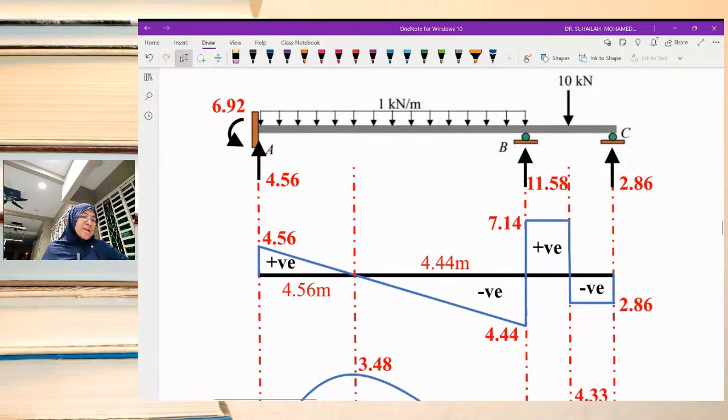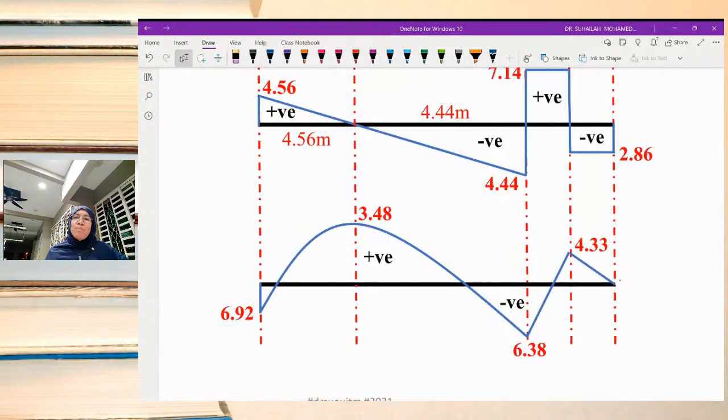The shear force diagram, for UDL, is inclined like this. Sometimes it becomes two triangles with an intersection. Sometimes it becomes only a trapezium. When there is an intersection like this, it will become the maximum moment in the bending moment diagram.